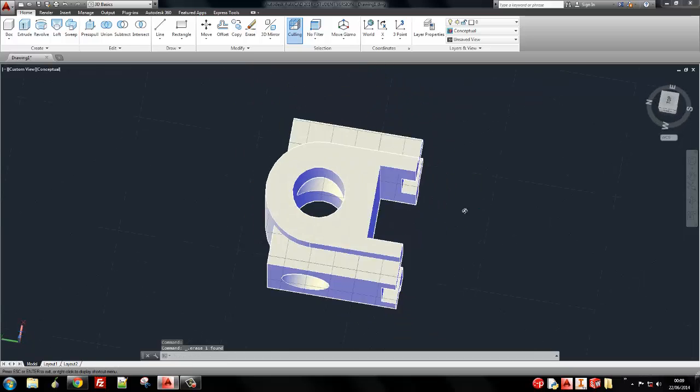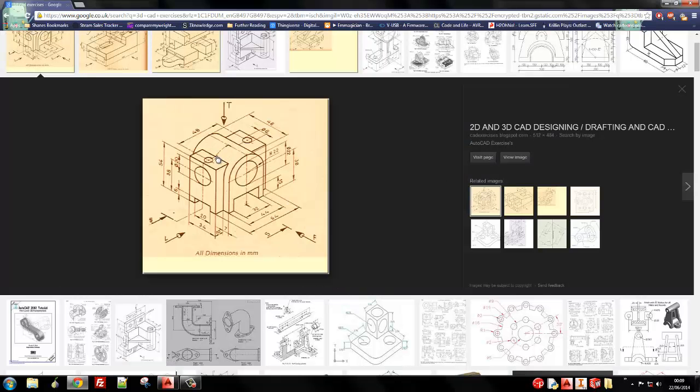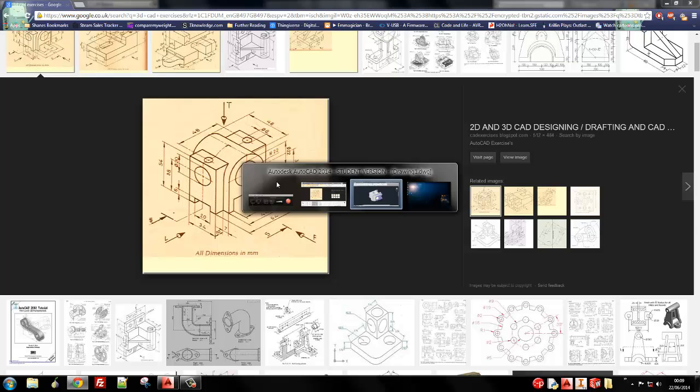Okay, I think the last part then is to put these two holes in the top here. Now you can see clearly that there are holes in the top, but it's also not showing you holes in the bottom, so we can only assume that the holes are penetrating the top but stopping when it hits this cut circle, this hole that's going through. So that's what we're going to do.